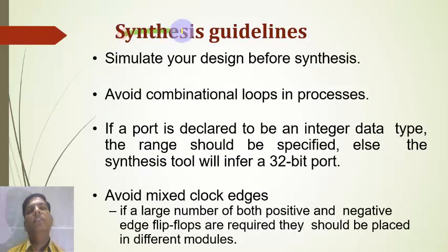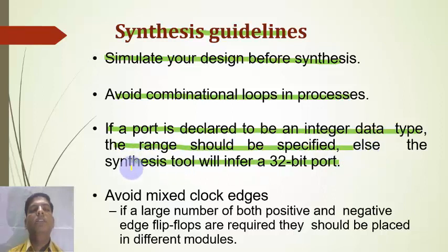Then some synthesis guidelines. Simulate your design before synthesis. Avoid combinational loops in a process. If a port is declared to be an integer data type, the range should be specified, else the synthesis tool will infer a 32-bit port.